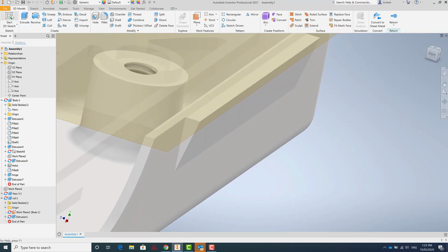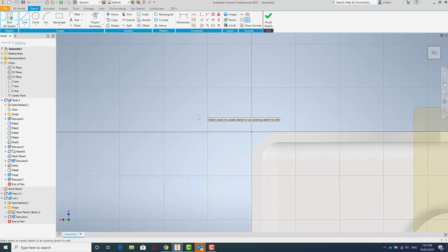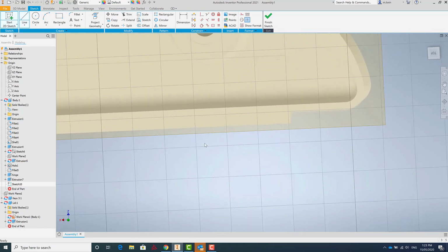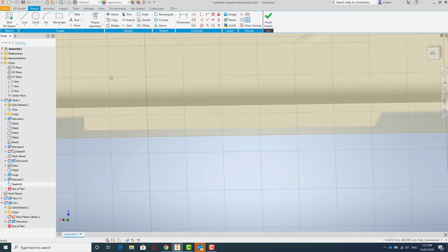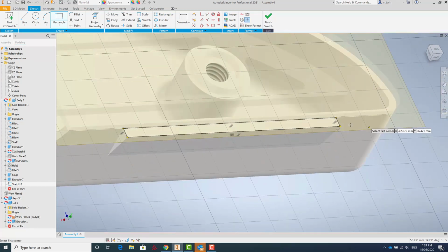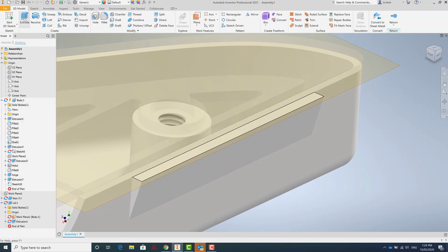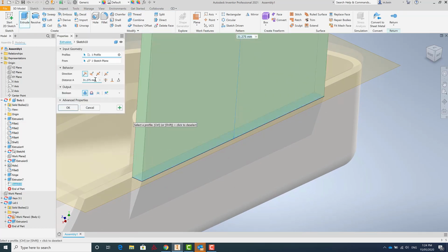And now I want to start a sketch. And I'll start the sketch here. Because I now need to create the vertical part of the hinge, where the hinge hole will be for the lid. So I'll come up here and we'll go a rectangle from here. Hinge barrel, that's the term I was after. Great, so I've got that profile there. Start the sketch, extrude, and I really want that to be probably no more than 2 millimeters high.